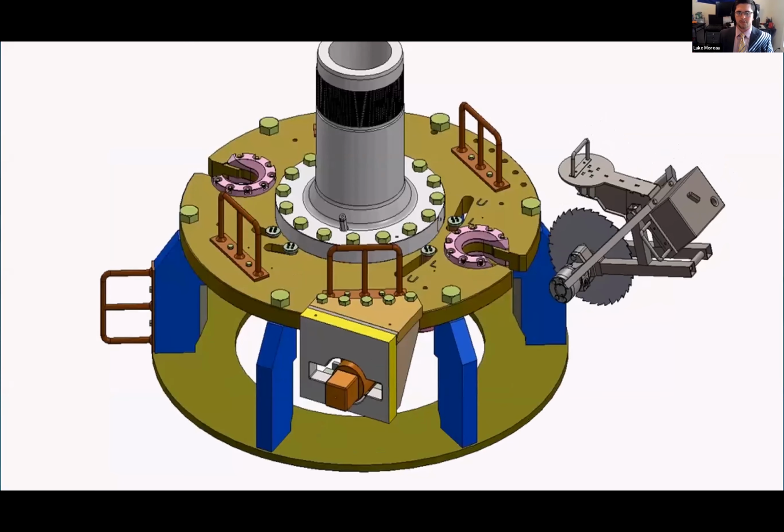Lastly, we did our maximum deflection calculation. We used a force of 200 pounds and a torque of 50 foot-pounds. As we showed you before, the torque that we calculated was only 36 foot-pounds. We used the 50 foot-pounds to be conservative, and we still only found a maximum deflection of 0.2 thousandths of an inch.